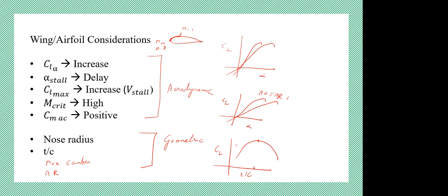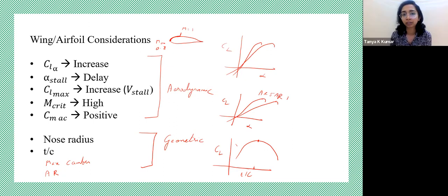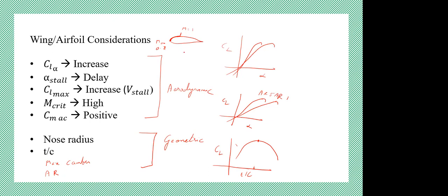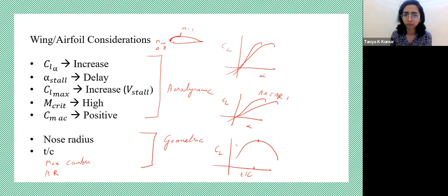Because of the shape of the airfoil. Yes, so because of the shape of the airfoil, what do you have? You have a change in the pressure distribution. So the pressure is reduced here, right? So when the pressure reduces, the speed increases, right? Yes, ma'am. So that is the reason. You're right. Shape of the airfoil is the reason why pressure reduces. So that is why you have a flow accelerating above the airfoil.